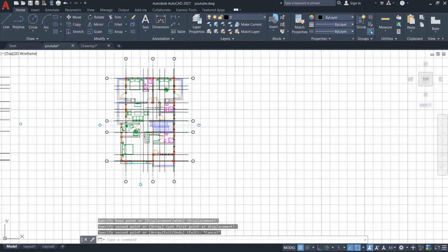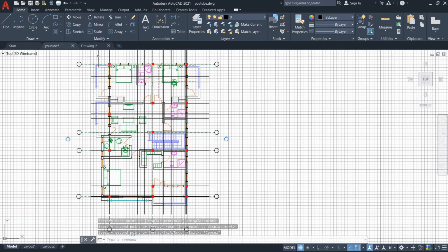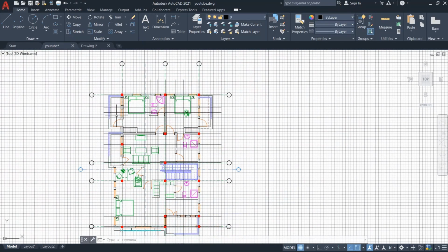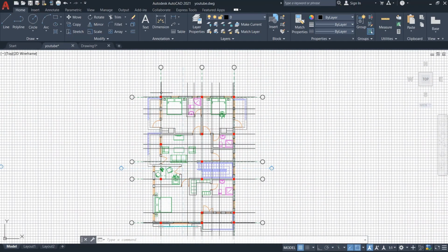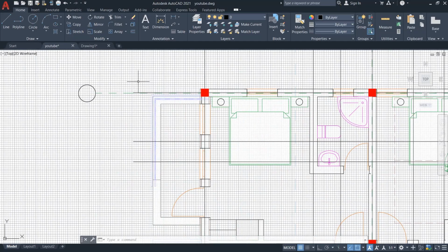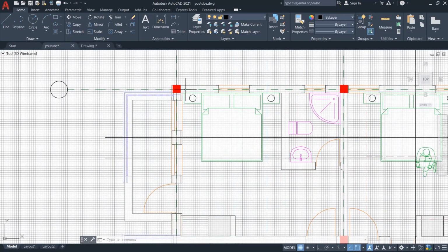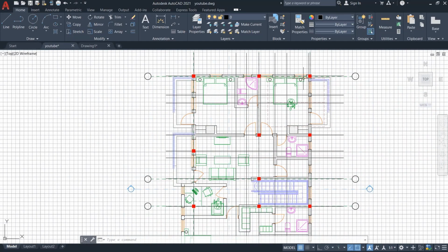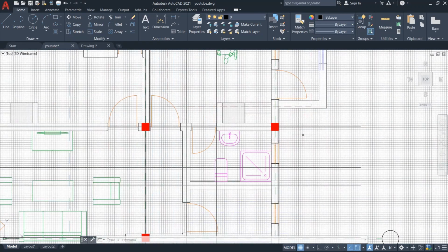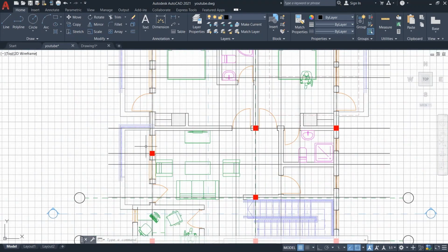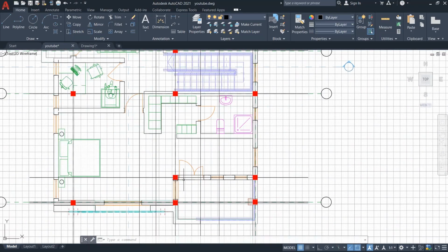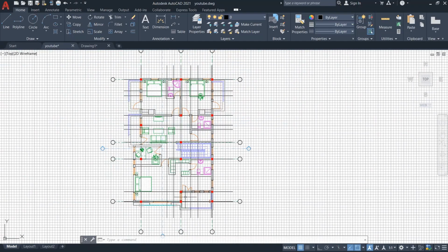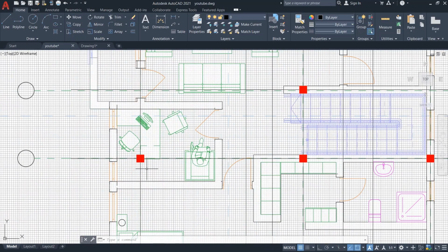Now remember, we talked about these cantilevers that are here. I've already taken note that there's going to be a cantilever. Okay, so I've superimposed this now. What we can see is all the columns are aligned with the walls around here. Everything is okay. Okay, we have an issue here, around here. You can see this column is inside this room here.